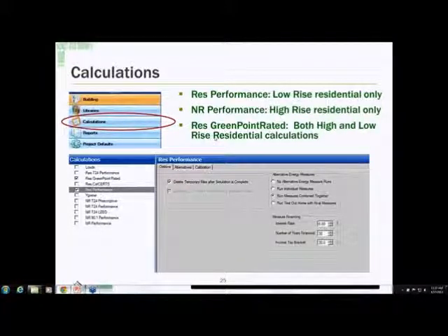But for best practices and for our program for the GreenPoint Rated, you want to not model out every single unit and just model out that floor level as a block load, and partitions as well, as they won't make any difference in the energy calculations.